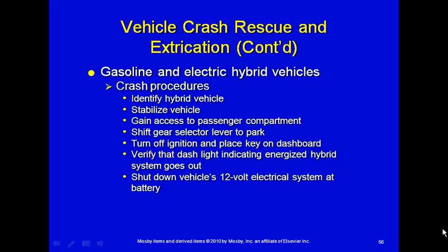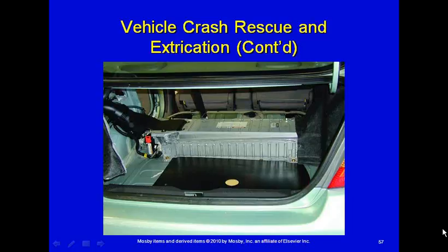As far as gasoline and electrical hybrid vehicles, identify the vehicle as a hybrid, stabilize the vehicle, gain access to the passenger compartment, shift the gear to park, turn off the ignition, place the key on the dash, verifying that the dash light indicating energized hybrid system has gone out, and then shut down the vehicle's 12-volt electrical system at the battery.